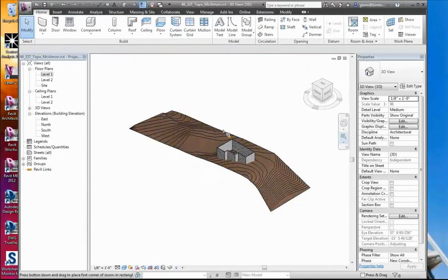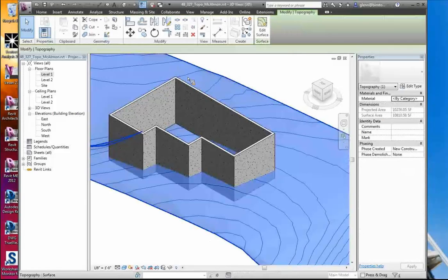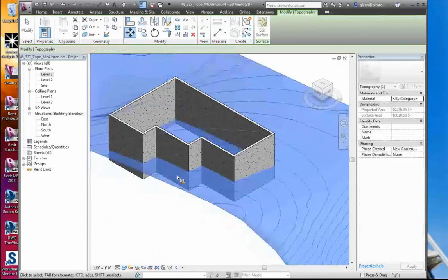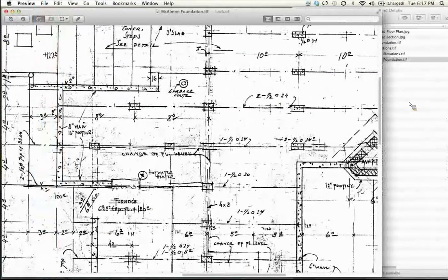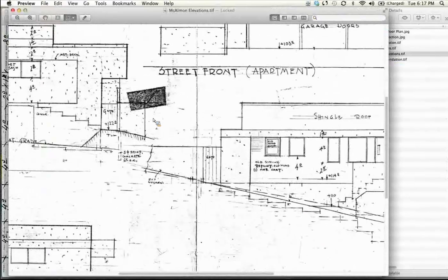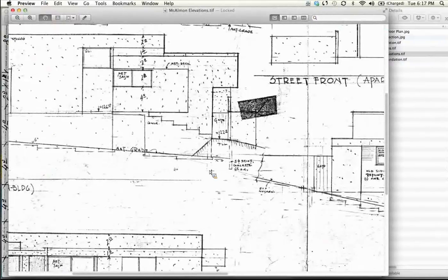Here's the deal. As we're doing houses like this, where the topography and the foundation walls are a little bit uneven with each other, we often end up having what's called a stepped foundation. How a stepped foundation looks is, you don't see it so well in this foundation plan, but if you go to the elevations, you can see it. We end up terracing down, and we basically have the bottom of the concrete follow the topography down, and we tend to do it in discrete steps.